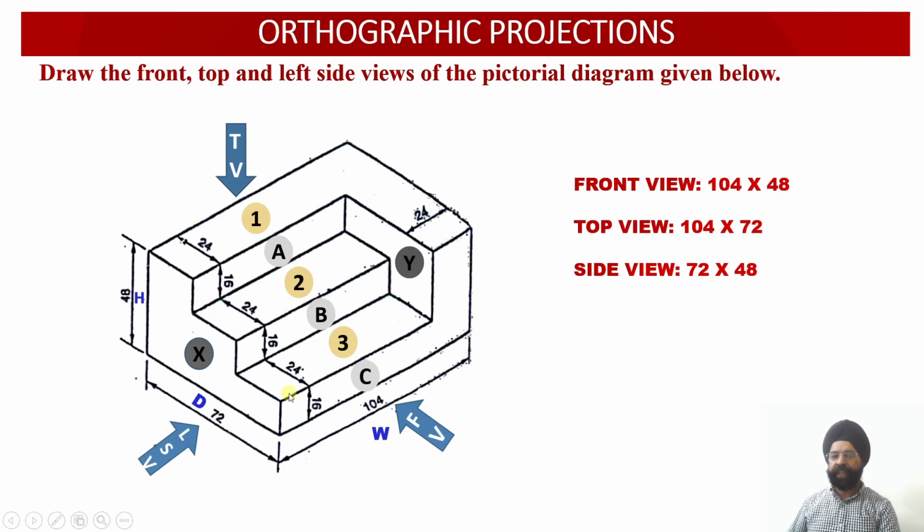And then you have the surface C, which is an angular surface. You can check, this is an angular surface, and corresponding to this surface C, once again the projections will be obtained on the vertical plane. The projections of surface A, surface B and surface C, as they are obtained on the vertical plane, will provide us the true shapes of surfaces A, B and C, since these surfaces happen to be parallel to the vertical plane.